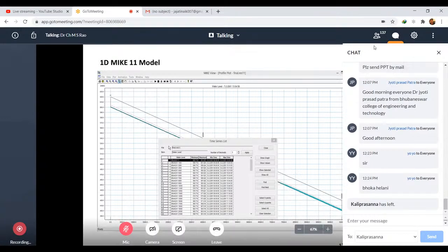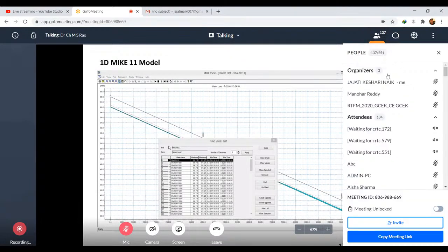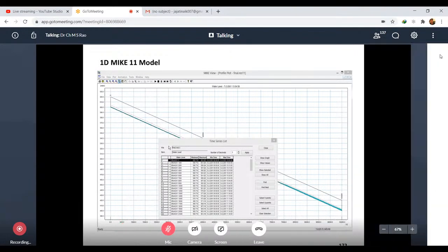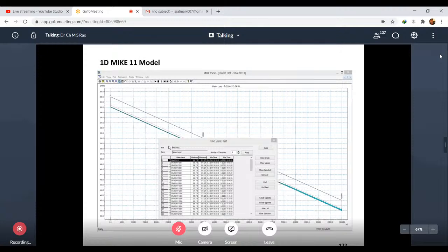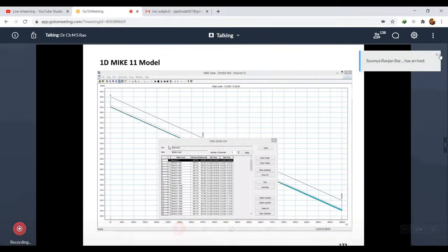You cannot calculate the discharge and stage at the same place. You will be calculating the discharge at the downstream side for the corresponding flow depth at the upstream side. You cannot get the same depth and same discharge at the same place. This is one drawback.